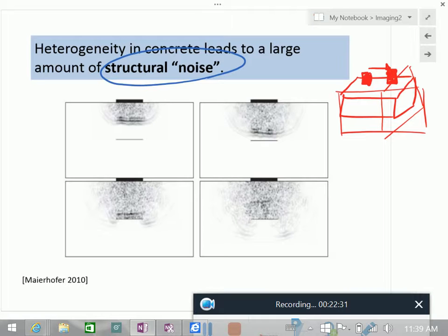We had talked about a spherical wavefront, right, for P wave, S wave. But here you can see that it's obviously much stronger underneath and kind of fades towards the end. Because transducers have directionality. Because of these two problems, B-scans are not the best kind of imaging in concrete.